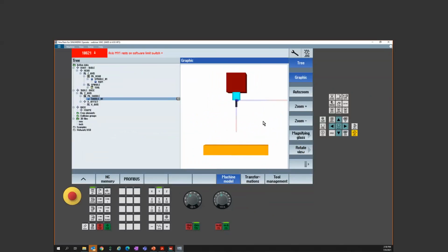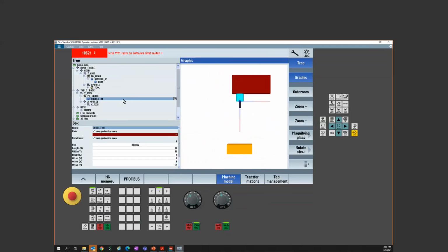Say okay. Drops my table down. It is centered in the Y, so that's okay. I don't need any offset in the Y. But right now, if I look at it, the way it's positioned, I would only be able to get my spindle to half of the saddle. So as I move away, I'm never going to get to the other side of the saddle. That's because I need a little bit of offset in the negative in my Y, that'd be my Y axis, sorry.